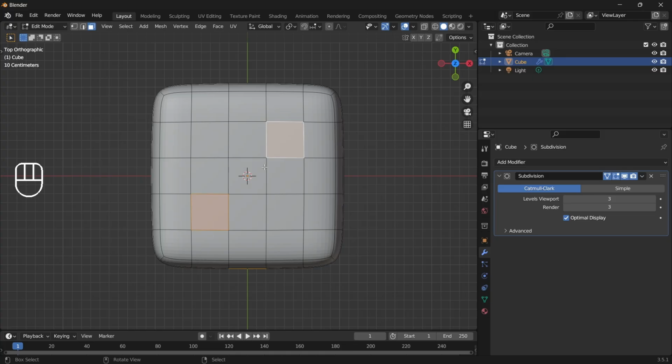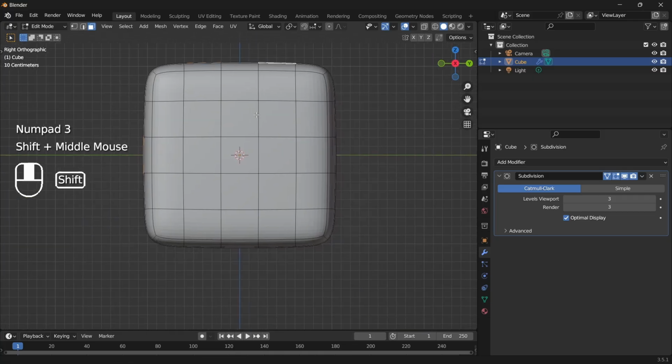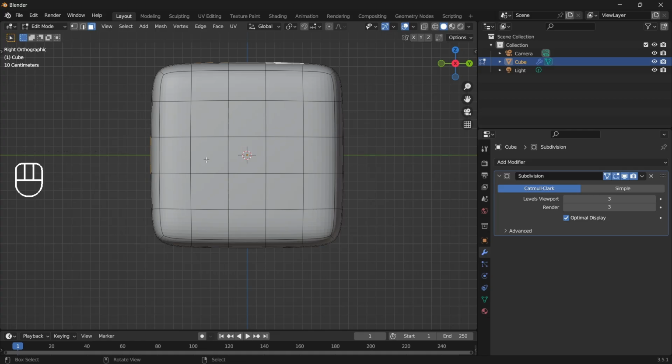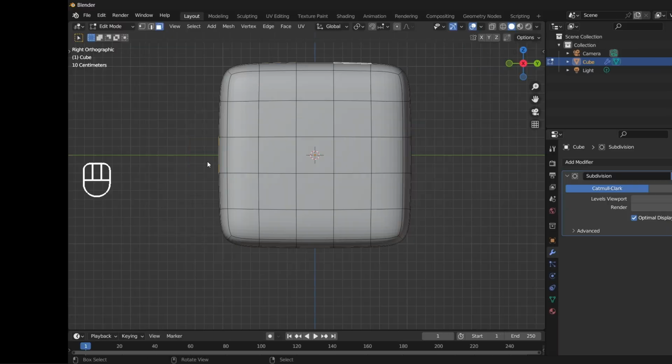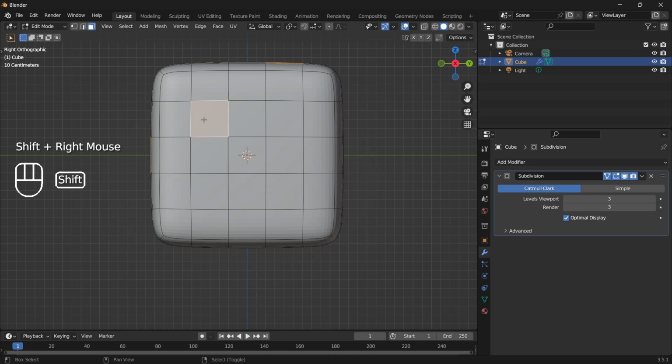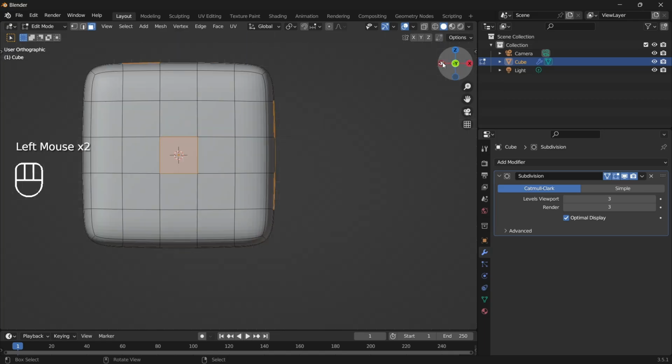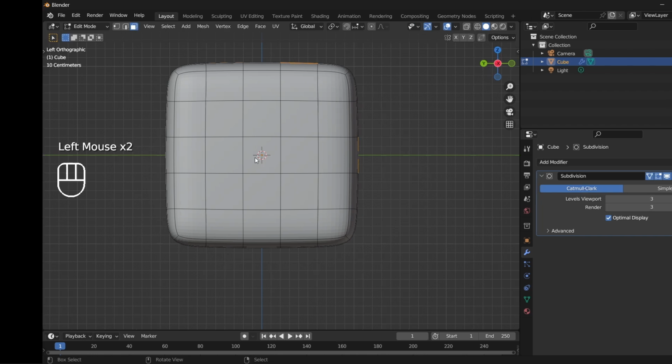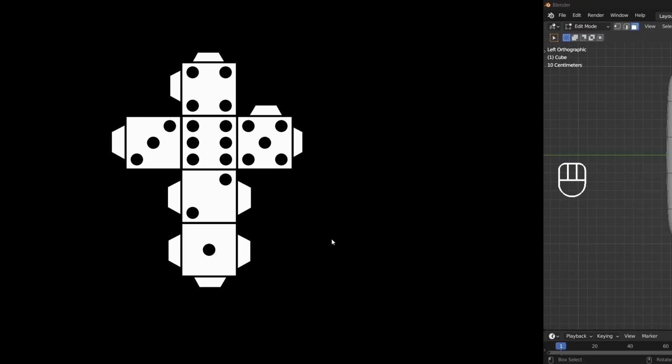If we press 3, we're going to come over to the right side, or our cube's left side. And this should have 5 divots. So we're going to select 1, 2, 3, 4, 5. I'll come over here to this gizmo and swap to the other side where we should have 3 divots.